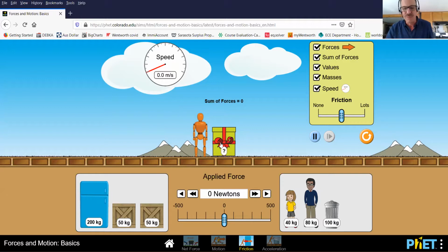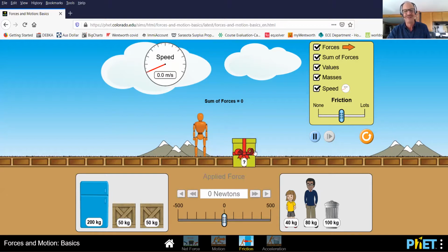I can divide by 9.81 meters per second squared too, but give me the mass of this questionable package. So that's three things you're going to do: the coefficient of static friction for this one, this one, and this one. This is all of about a 10-minute lab, by the way, if you do it correctly and you've got a calculator in front of you.